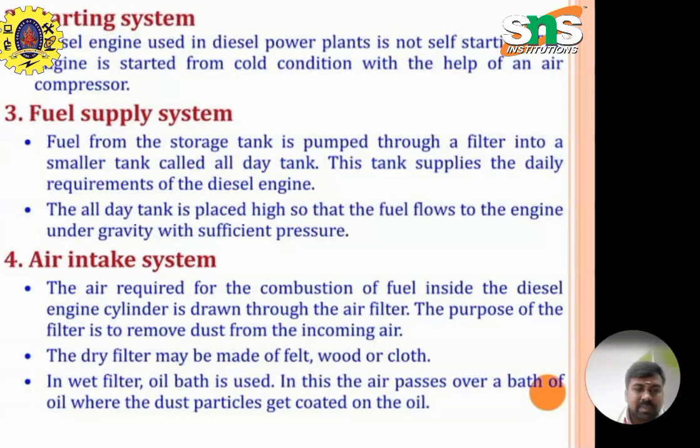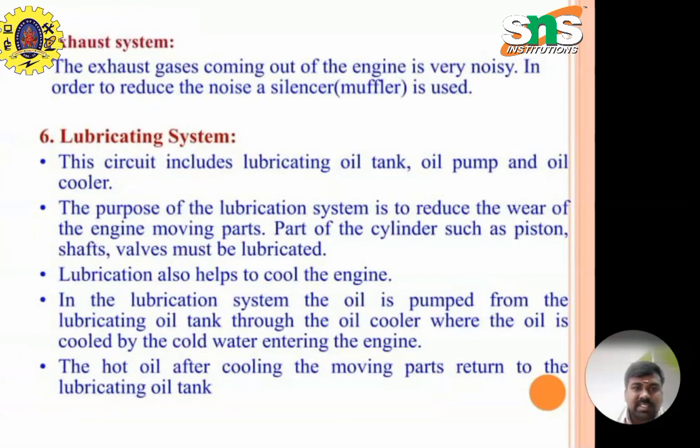The air intake system. The air required for the combustion of fuel inside the diesel engine cylinder is drawn through the air filter. The purpose of the filter is to remove the dust from the incoming air. The dry filter may be made of felt, wool or cloth. In the wet filter, an oil bath is used, where the air passes over a bath of oil and the dust particles get coated on the oil. Exhaust system. The exhaust gases coming out of the engine are very noisy. In order to reduce the noise, a silencer, that means a muffler, is used.